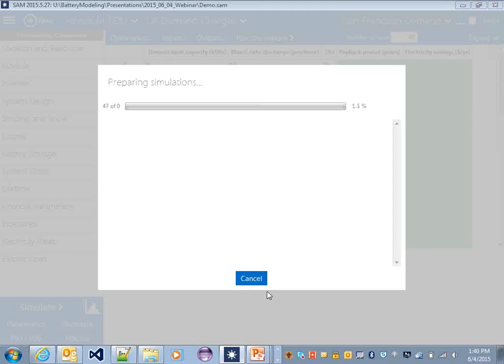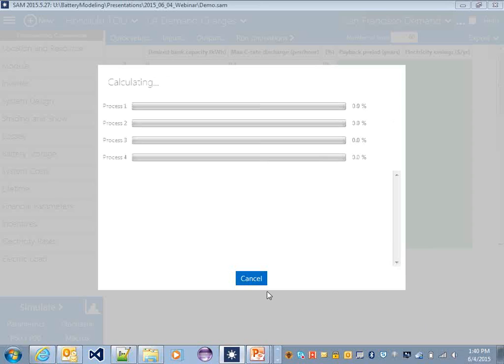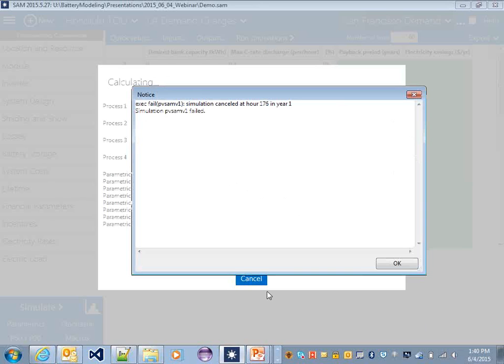But within this commercial utility rate structure that has demand charges, I was able to find some cases with this current dispatch scenario where, by varying the size of the battery bank as well as how much energy it was allowed to discharge over each time period, it actually would make sense to put a battery in. So I can only imagine that by adding a more optimized or automated control strategy for peak shaving, that benefit would just become more and more apparent.